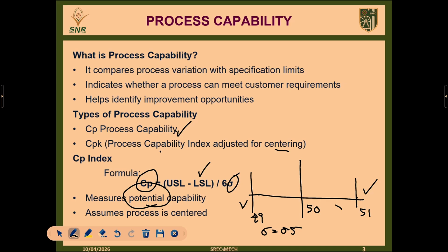While calculating this, we can understand the difference between what is our specification, what is actual. This difference, the deviation between the actual capability and expected requirement. So these deviations we can calculate using the process capability. Based on this process capability in number, we cannot ensure that the process is within the control. There is a possibility that process may deviate from the required specifications. This deviation cannot be understood from the CP, process capability.